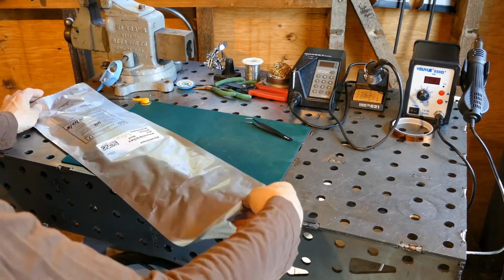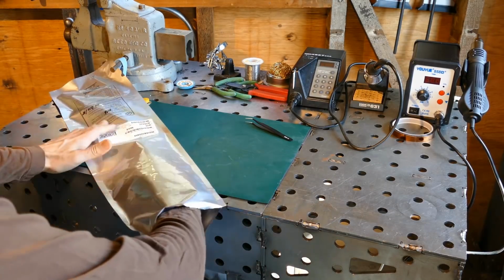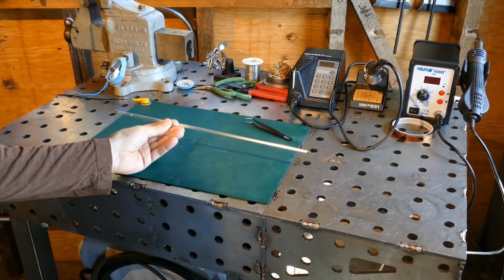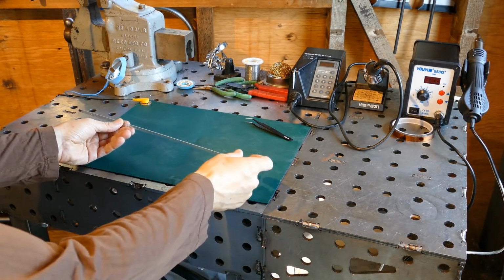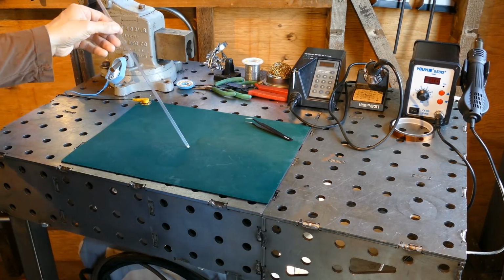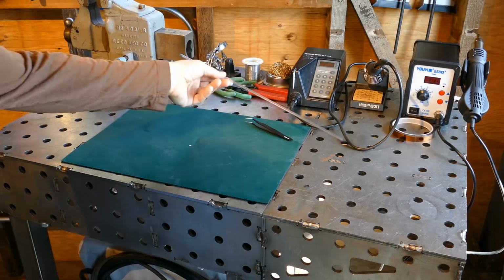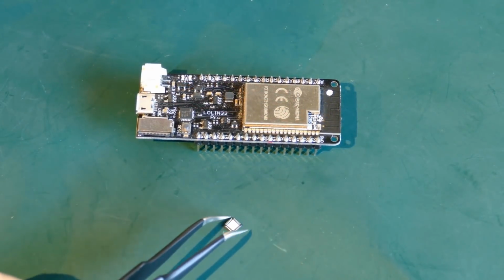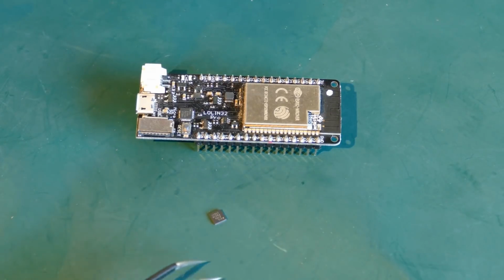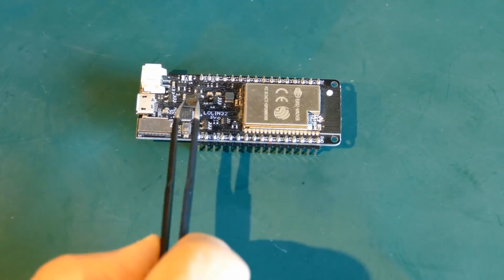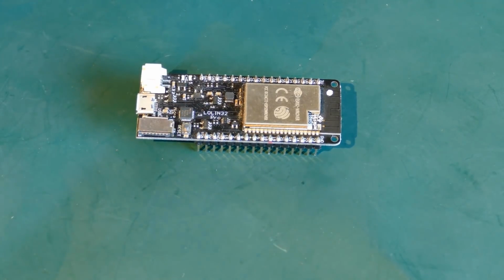When I got home today, I found a rather large box on my doorstep containing this long ESD bag, the contents being this chip tube, which contains a single CP2104. I appreciate all the ESD protection, but not the most efficient packaging. The chip is only 4 millimeters square. Before I remove the old chip, it's important to note the pin 1 orientation, which is indicated by the little dot in the corner. The 858D is my first hot air station. This little chip may not have been the best choice to break it in.